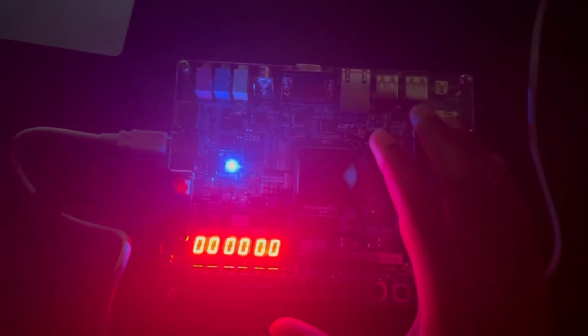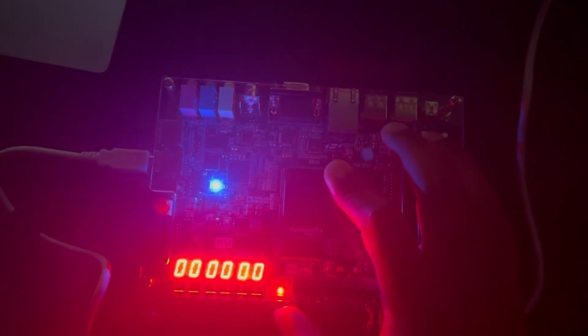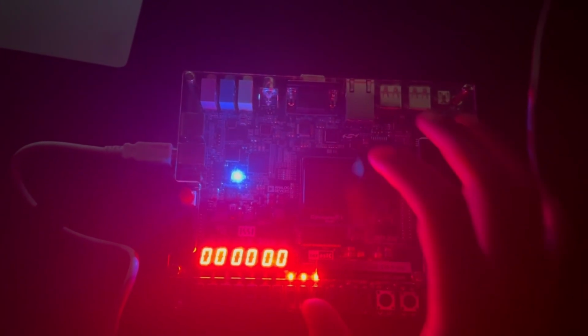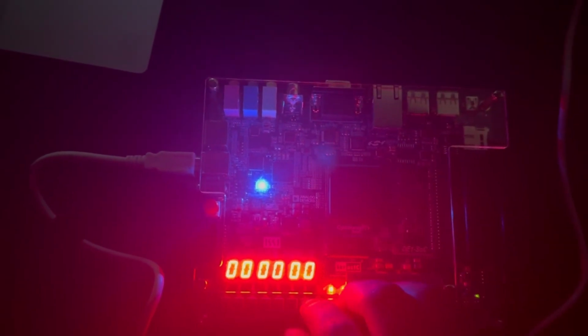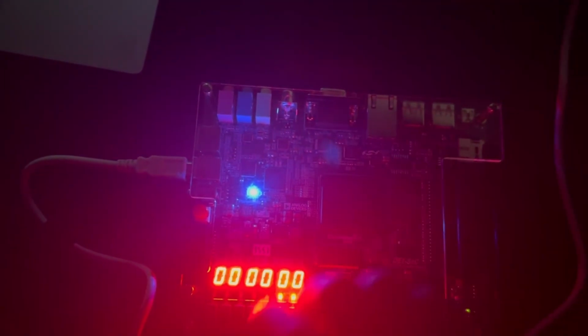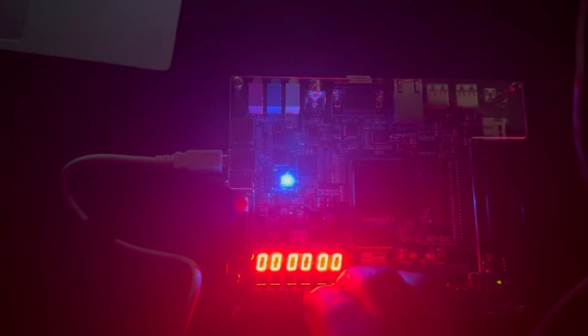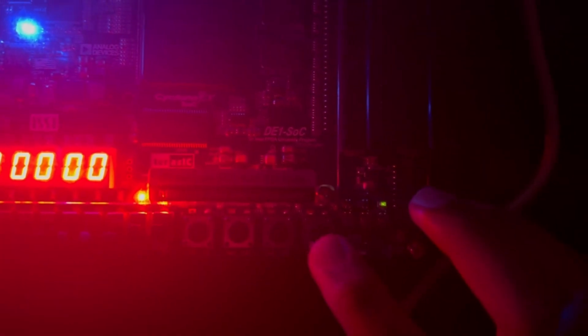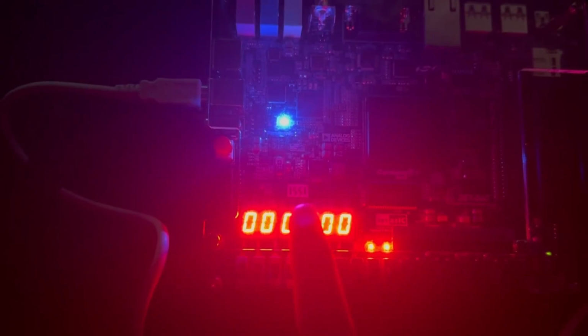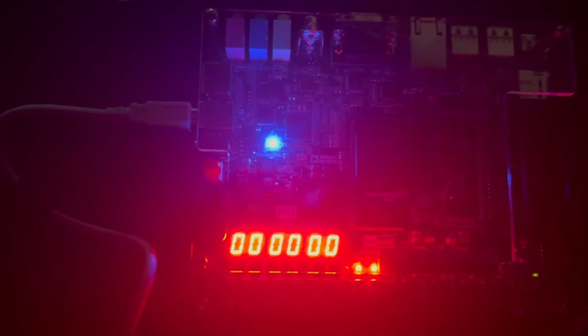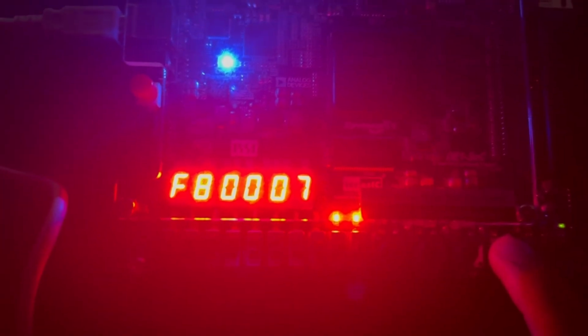As we can see, I have successfully implemented the program here, and just like I explained in the program, this was a sanity check. I have assigned the pins, switches to the LEDs. You can see as I turn it on, it's turning on, so that is the sanity check. Here is the key 0, which is coded to basically reset or send test data. So as I change it, you can see the data changes.